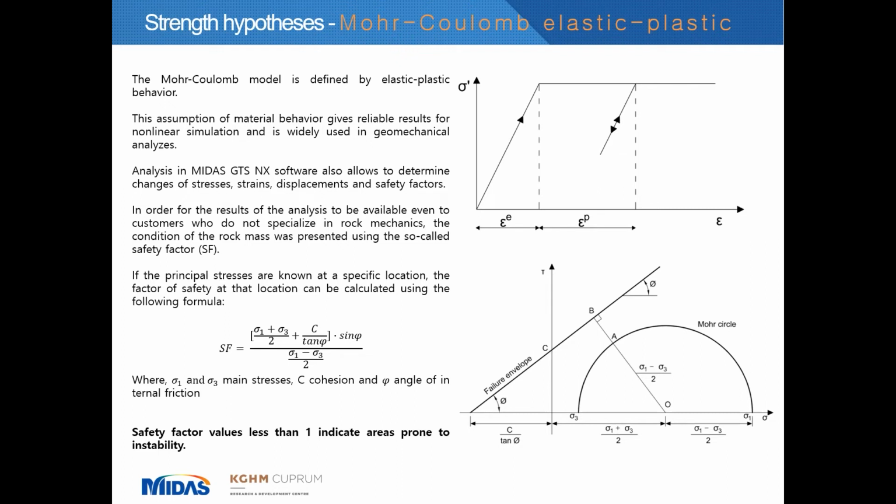Nevertheless, I would like to point out that according to our experience, in the case of modeling the stability of underground objects in the dynamic load system, unfortunately the Mohr-Coulomb strength criterion seems to lead to incorrect results, but still this is not the subject of this presentation. In the static load system, I need to highlight it one more time: the Mohr-Coulomb criterion is one of the most credible approaches.